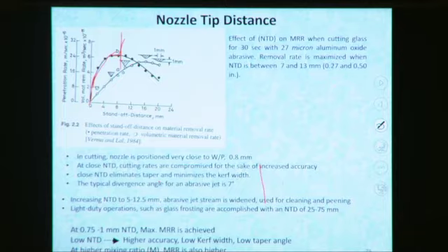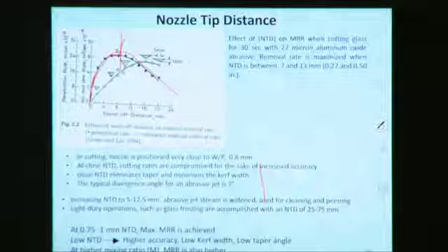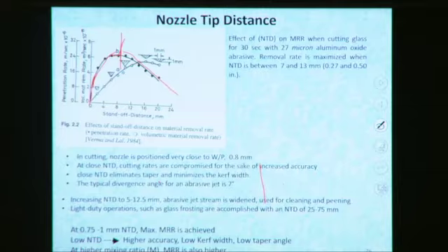After that, if we increase the stand-up distance, the penetration rate will reduce, because of the interaction of the abrasive jet with the outside air.